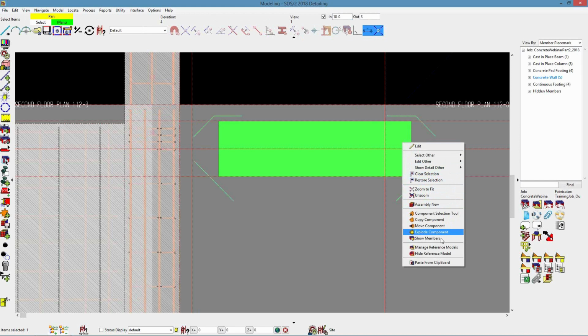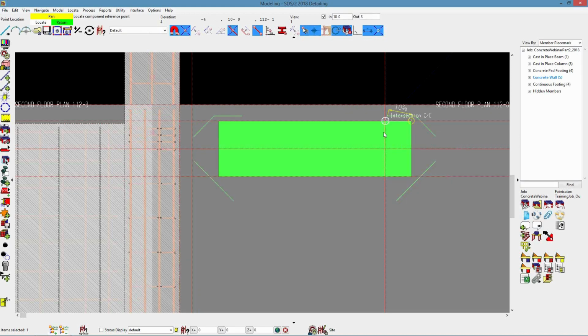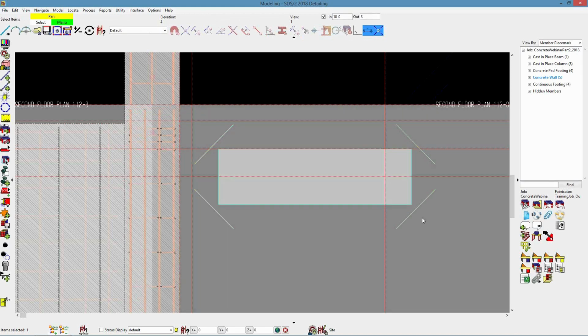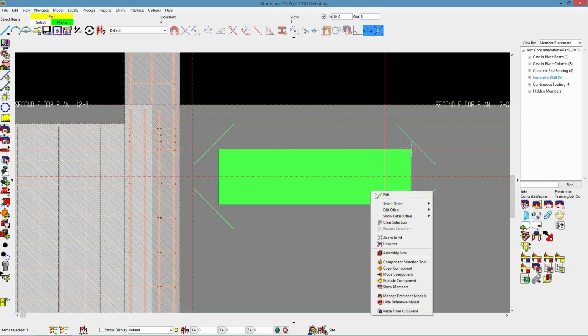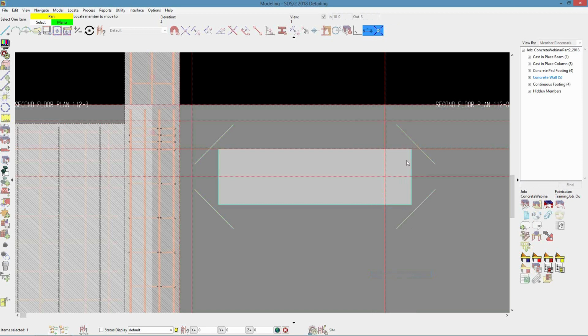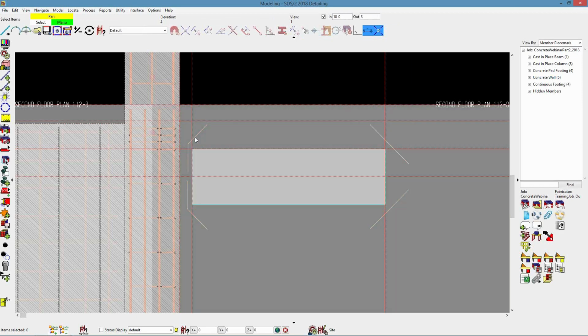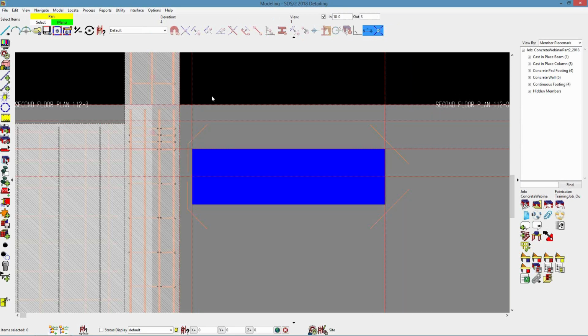I can go ahead and move the component again here. Now you'll see that it's straightened out everything. It's got plenty of room. If I go ahead and move this component maybe back over to the 1 foot mark, now you'll notice that just this side has the reinforcements, or the bent reinforcement. So we do recognize the edges of the wall with your concrete wall opening reinforcements.